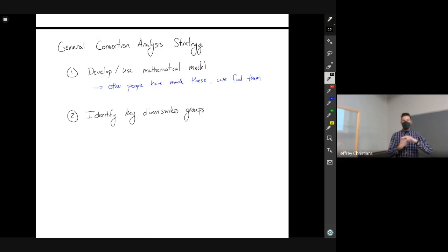So we'll learn fairly shortly if gravity plays an important role in the convection process. If we have free convection happening on the wall, gravity matters, and then we have to take gravity into account. So that gives us a new dimensionless group called the Grashof number. But we have to figure out what the important forces and physical mechanisms are in the specific problem that we have.